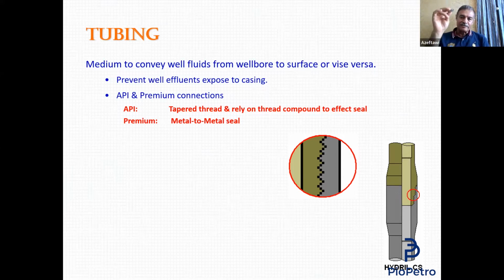And that's why this type of thread, you have to check it from time to time. So you have to go with a digital caliper. We have to measure the distance between each thread and the other. We have to measure the depth of each thread. And we collect these measurements and compare them to the table for this thread. If it is within the margin, then this thread is okay. We do this for both male and female to be sure that the thread is in good condition, because your life is here also. If you apply 3,000 psi and it fails, you die, simple as that.